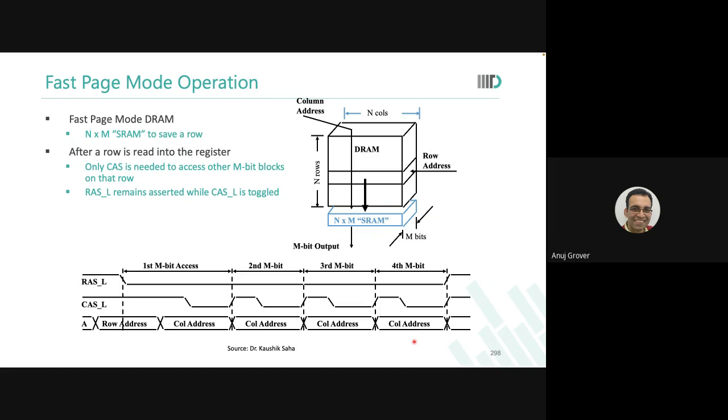That is also limited by the speed of the SRAM over here. Because in a burst mode, now you're not touching the DRAM RAS or CAS part. You're just reading the next word from the SRAM. Are you able to see this? This is actually much faster than what DRAM would have done. So the SRAMs are faster. But this is what defines it, limiting the area.